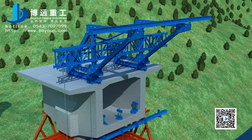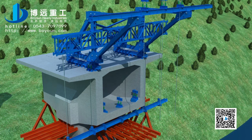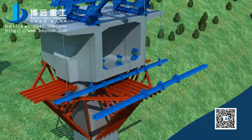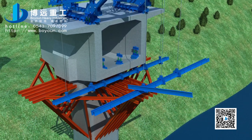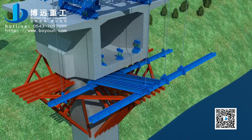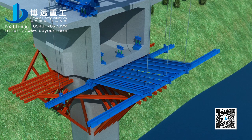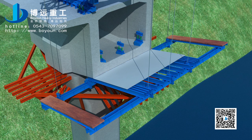Install the front upper cross girder, weld and connect to the diamond frame. Install the carrying pole beam and hanger rod. Lift the front joist and fix it on the front upper cross girder through the hanging system. Install the bottom longitudinal girder according to the space, specification, and route number of the forming traveler installation drawing, and weld it on the front and rear joist. Then, install the bottom framework and walking platform.